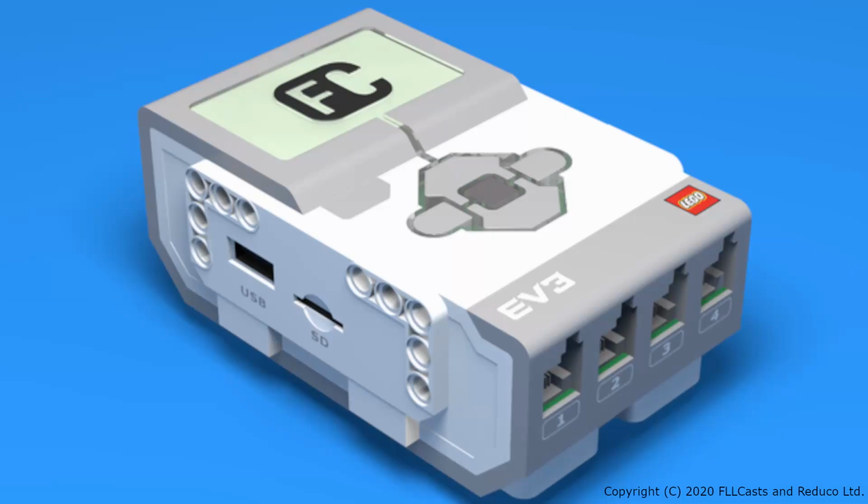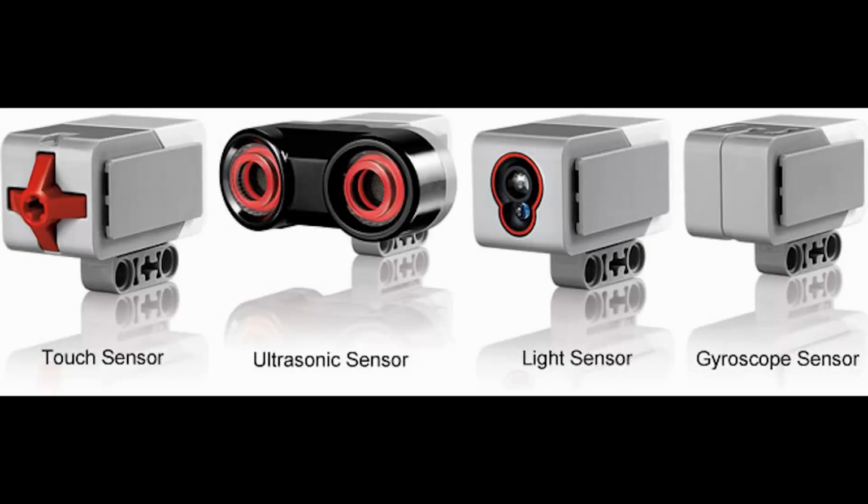The ports on the bottom will be labeled 1, 2, 3, or 4. These ports are for sensors. There are 4 different kinds of sensors: touch, ultrasonic, light, and gyroscope. The touch sensor detects when the front part of the sensor, the red part, is pressed. It can be used in a variety of ways. For instance, to detect when you are nearing a wall so that you can turn away, or to detect when you've reached a mission on the field so you can tell the robot to complete it.